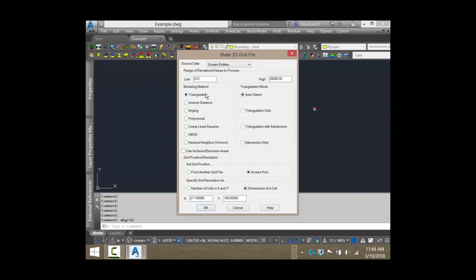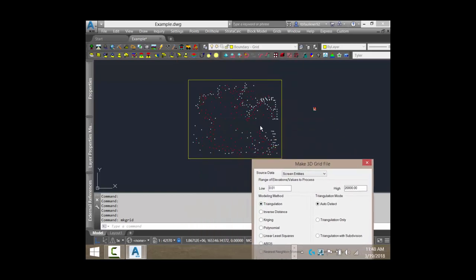And another thing on the triangulation method, this is not going to extrapolate outside of the area. So inside of here, we can calculate elevations between known data points. Whenever we get out to the corners here, we can no longer interpolate. We would actually have to extrapolate. And on its own, the triangulation method does not do that. So our contours are just going to be within the drill holes, and that's fine for this slab.